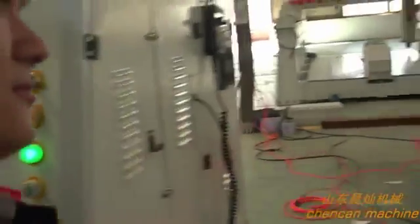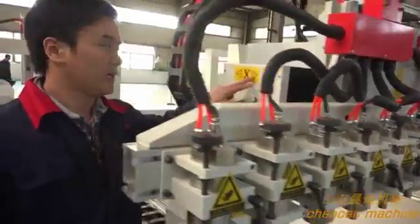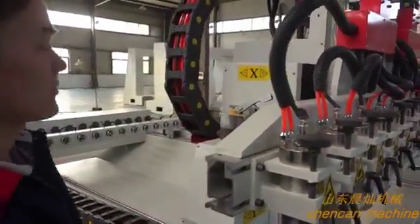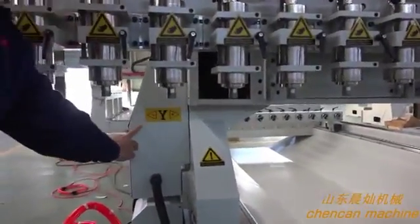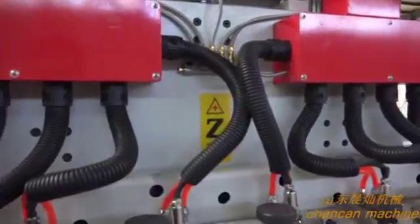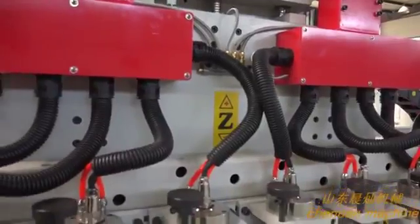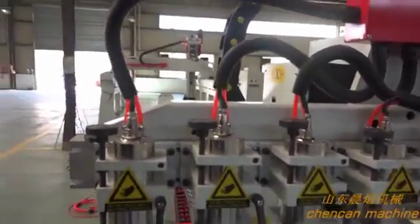Now we should make sure that on this machine, X minus is going this way, in front, and Y is like this. The Z is here. If you don't know the direction, you can check here and here, 3 axes, and also there is a rotary. The rotary is no problem. Now we check it.